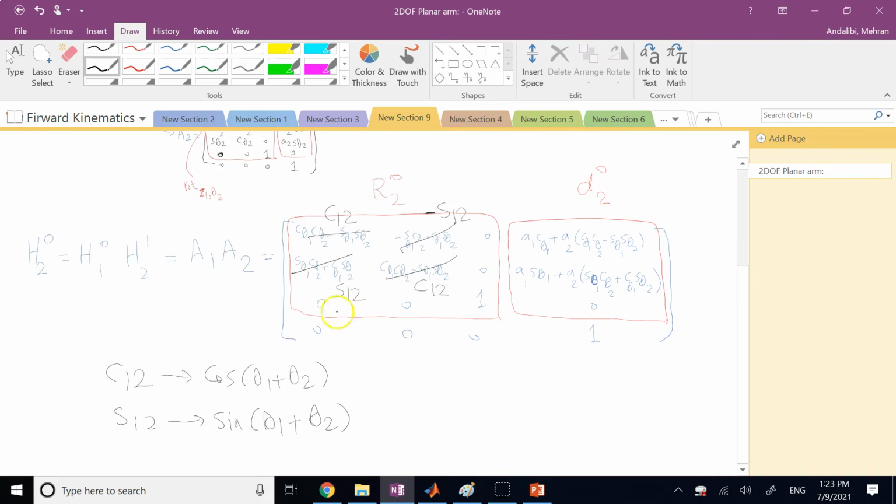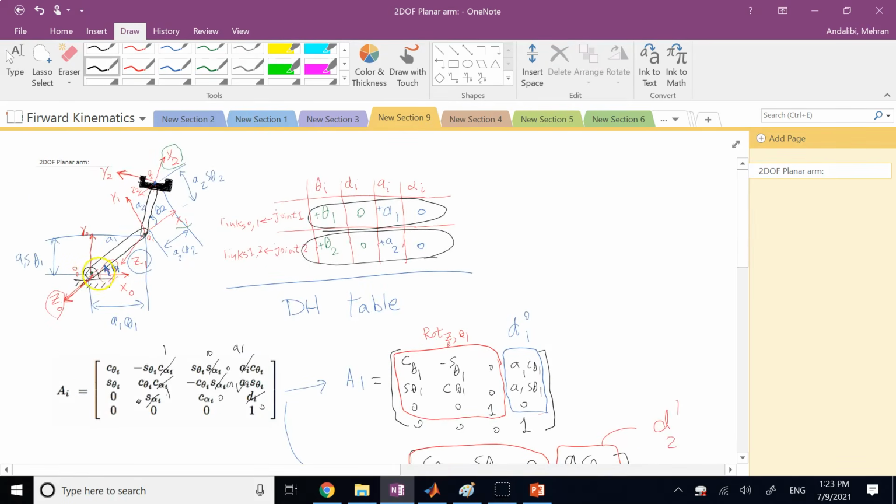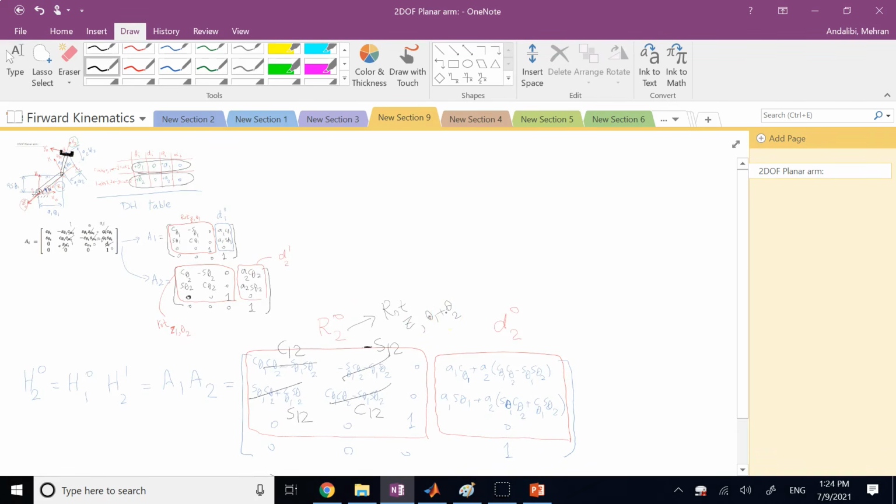So now what kind of format is it? Definitely it's a Z matrix. So this is a rotation Z matrix. And what is the angle? Well, the angle is theta 1 plus theta 2. Is that right? Absolutely. Because if I want to go from the orientation of frame 0 to frame 2, all I need is 2 rotations: one time at theta 1 about Z, and then at theta 2 about Z. Since they are in the same direction, I can simply add them together. So by a simple rotation about the Z0 axis with angle theta 1 plus 2, I can align my frame 0 to frame 2. That's all I need. They share the same Z, and their x's and y's are rotated by a simple Z of theta 1 plus theta 2. That's all it is. Okay.